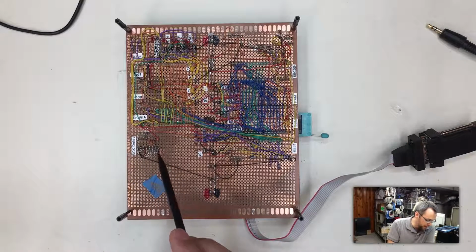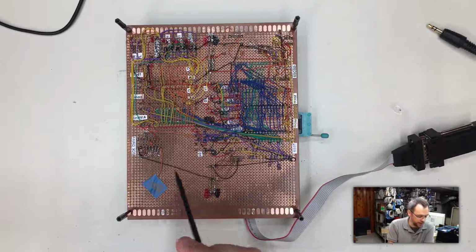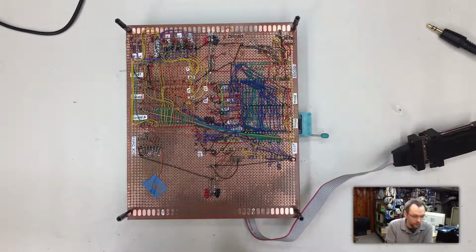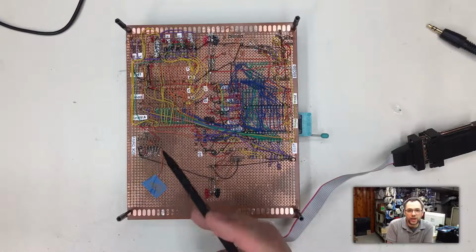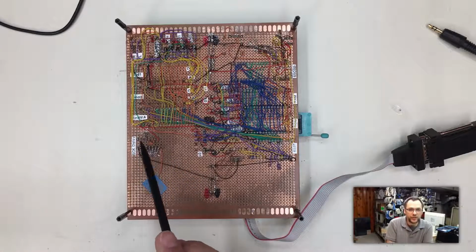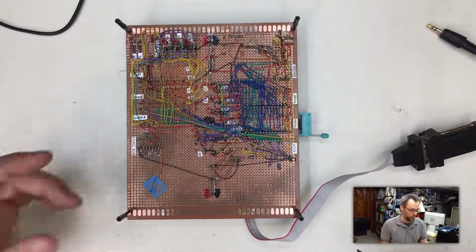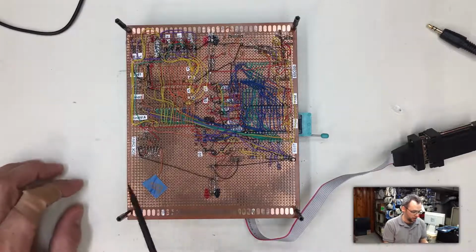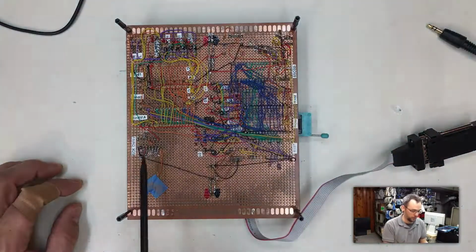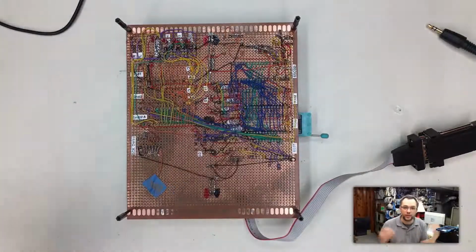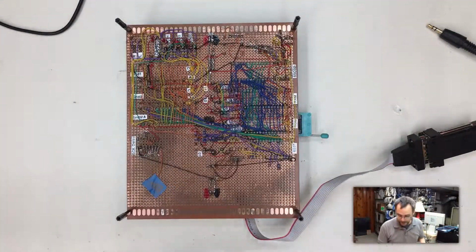Well, this delay allows you to use mode 0 because it delays it that half clock. So you could theoretically connect that up and make it work on mode 0. This can be an issue at super high speeds though, and this circuit is designed specifically for a 1 megahertz system clock, or 1 megahertz bus clock here. So if I were to change the frequency of the computer, this delay would no longer work. In my case, that doesn't matter, because as you can see, we're clocking that straight out and it just works. So great, I don't have to worry about that delay circuit.